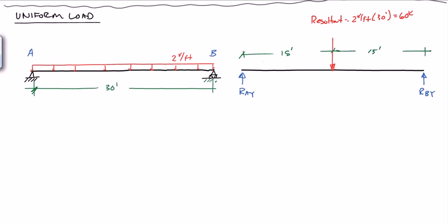And we get a horizontal reaction here. And I'm showing this because if there were many more loads, it might not be obvious what the solution is. So let's go through and do it. Sum of the forces in the x direction equals 0 equals RAX. So RAX is equal to 0.